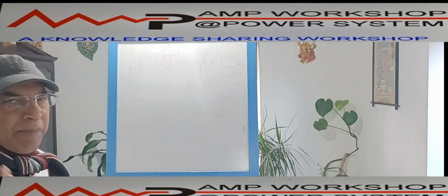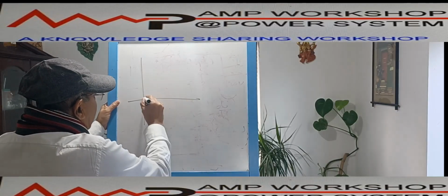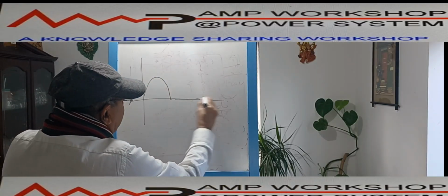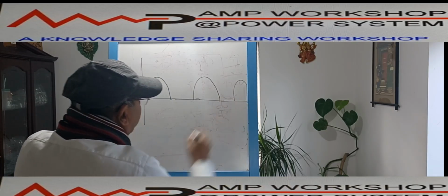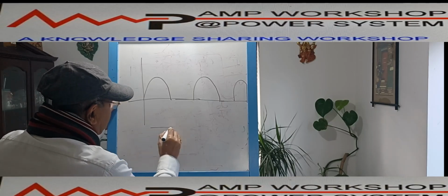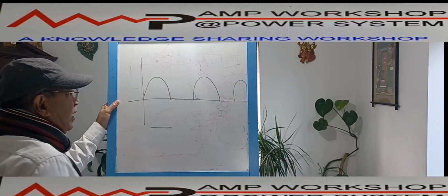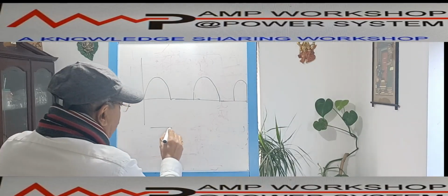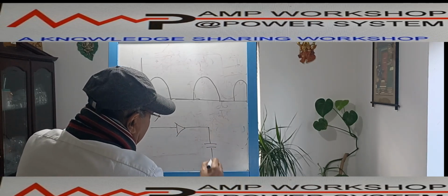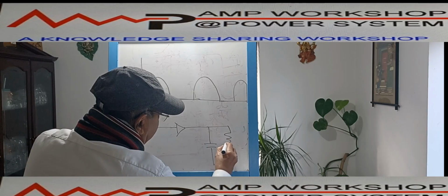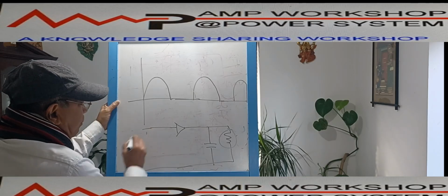You know, in the case of half wave and full wave, we have seen the voltage profile. In the case of a half wave rectifier, the voltage profile is like this, where one half is not there. Now this voltage has a sudden change. This sudden change we can make slightly smooth. How do we do that? We put a capacitor across the load. Suppose this is my lamp or inverter, whatever is there. Here is the input voltage.